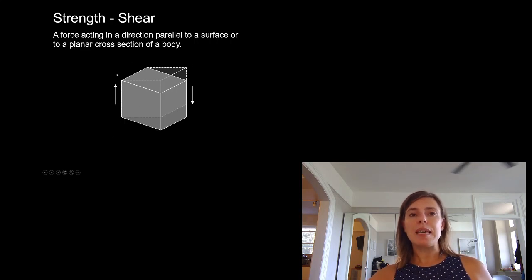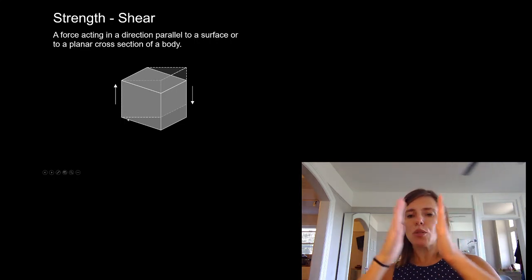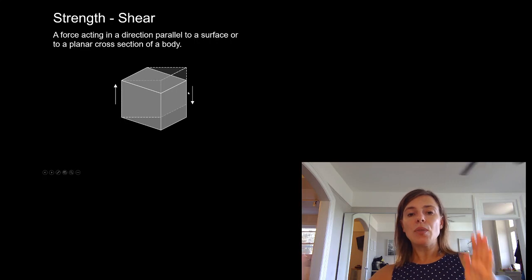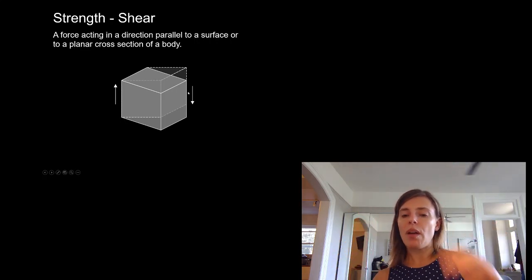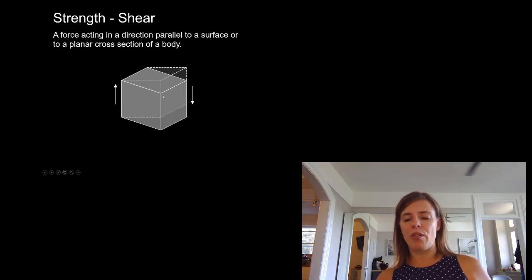And that's what you see in this drawing right here. You see these two arrows could have been put side by side right on this singular plane, but I'm showing it spread out a little bit to show you an accumulation of slip along a series of planes. And you can see it's making one side go down and one side go up. And we're getting this weird thing where a square starts to switch into a diamond. And that's going to be important again later in the term.